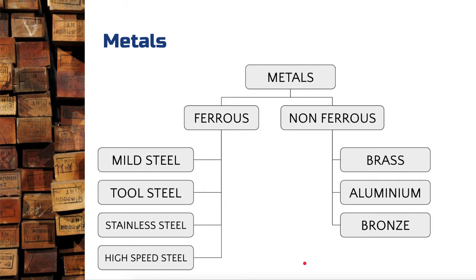You may use metals, a range of different metals, but you may use some of the decorative ones like brasses and bronzes, or you may use steels and things like that. Okay. Particularly if I'm thinking about where would I use metals, maybe in brackets, corner brackets to help hold my project together. Where would I use the more decorative ones? Brass, maybe my concealed hinges might be made from brass. Maybe my handles made from bronze, things like that. You may also use them as decorative surfaces, okay, so to add an extra element of decoration to your project.